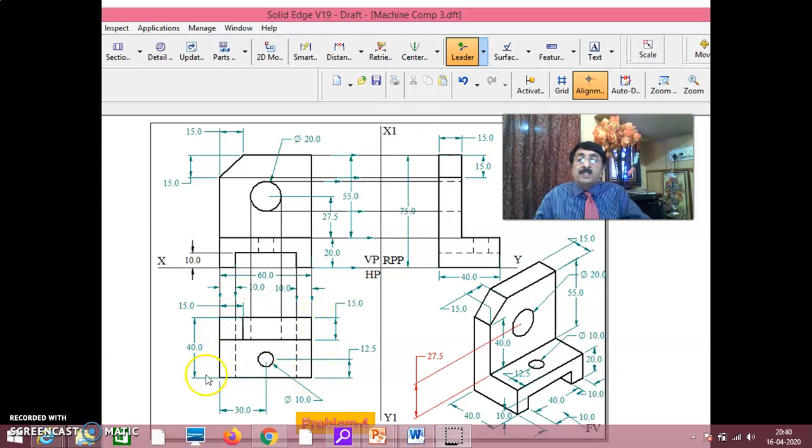That is very important. First you complete the rectangle. Once you complete the rectangle, you see carefully. Now, once you complete the rectangle, you write the fold here. This fold is 12.5. That is, from here, at the center it is located. At 12.5 is the center. At that center, you draw a circle of diameter 10. In that way, if you take the projectors up, in the front view also, this dotted line if you show, the front view will be completed.